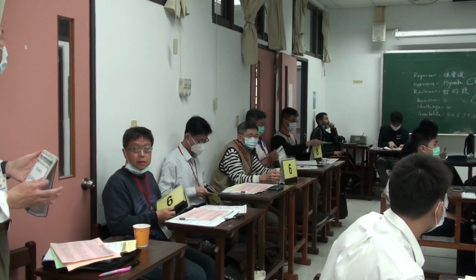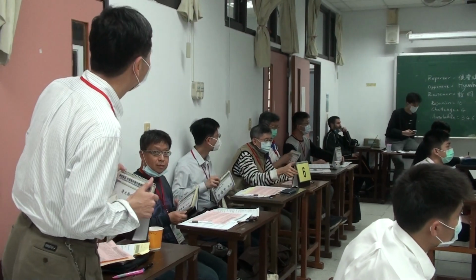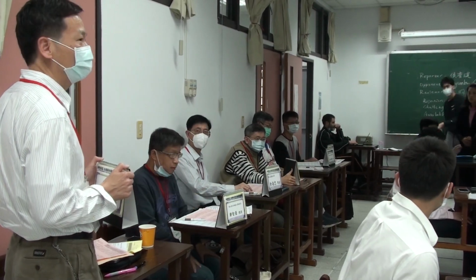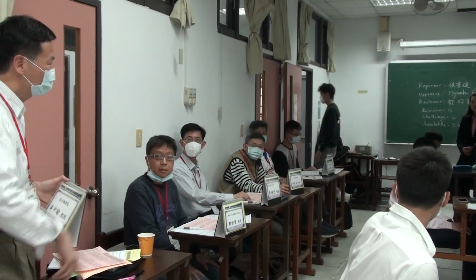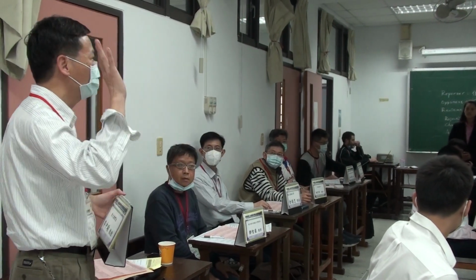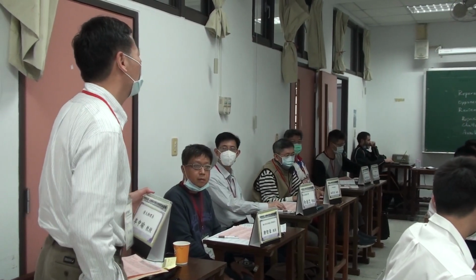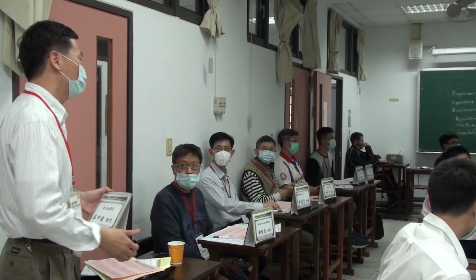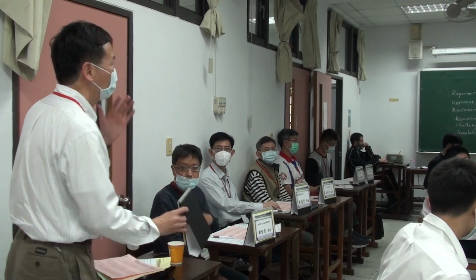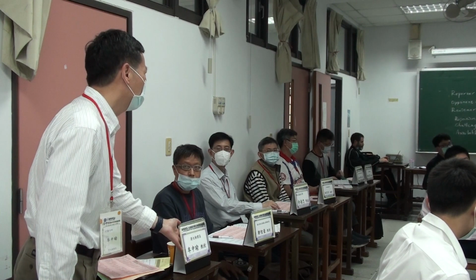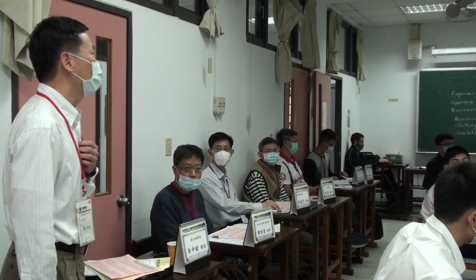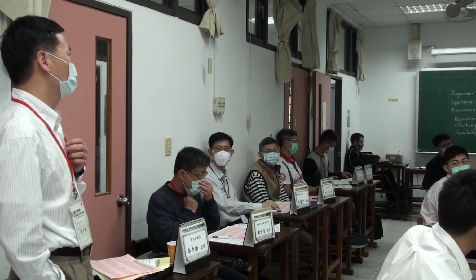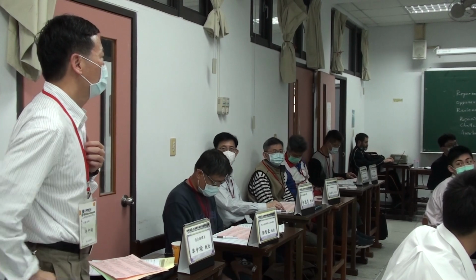Right, so any comment do we want to make? I just want to make a comment. As I said, the whole problem should try to find the relation between the temperature drop and the current velocity first, instead of starting from the King's law for fitting. Right, so that should be the spirit of this problem. Actually, in the King's fitting, the exponent may not be 1/2, 0.5. You are treating that as a fixed number, so probably that's one of the sources of the error. Right, so that's my comment.